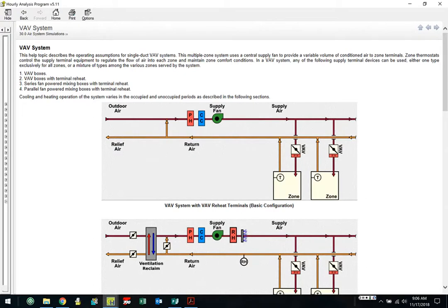The reason they do that in larger buildings is that they are always predicated on having a cooling load somewhere. So they'll put out 55, 57. It could get up into the 60 degrees if they can do a reset schedule with newer control systems. If there's not a large cooling load, we might not need 55 degree discharge air. We might be able to go a little bit higher. When we go a little bit higher, we get more airflow through the building, and it tends to work a little bit better for the people inside the building.